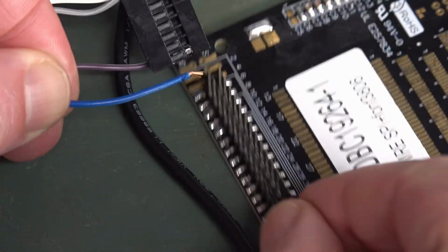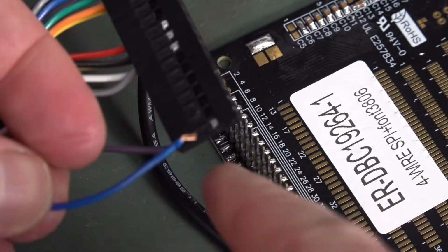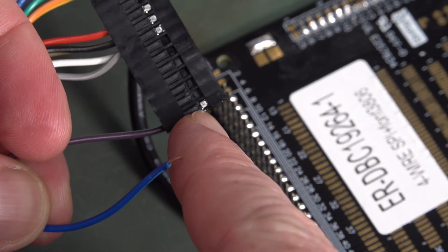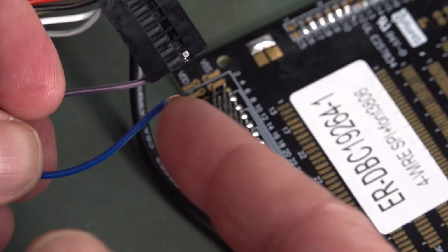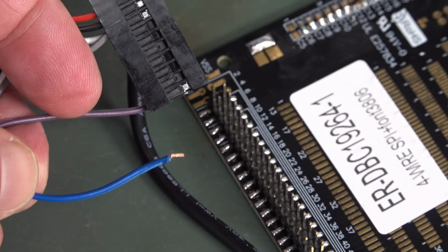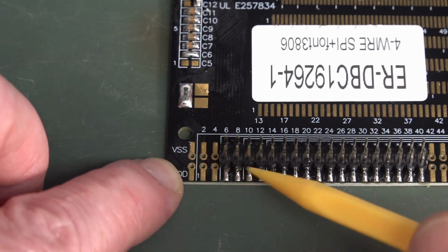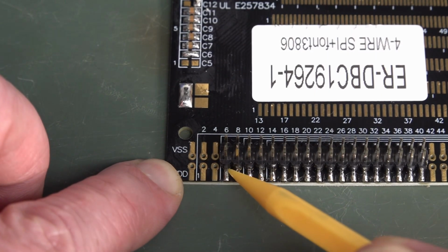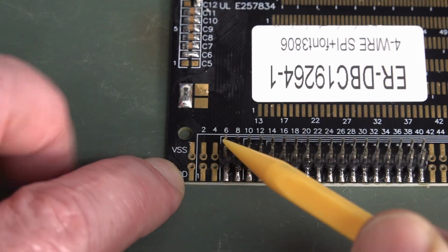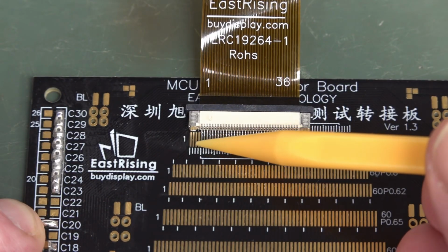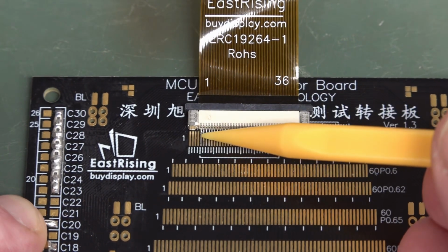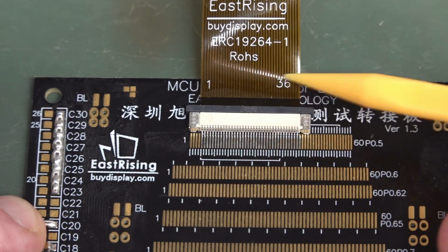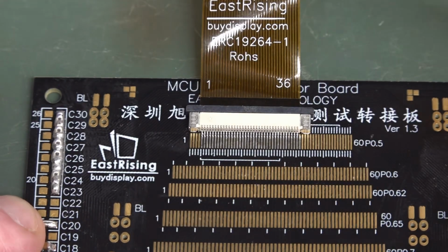And I thought I'd measure the battery current, but I've just come a gutser. I tried to pull the pin out here, which is the positive power pin, but the actual clip didn't come out and I pulled the wire out. Oops. One of the annoying things is that they've actually offset. They haven't put this right over to pin 1 over here. They've soldered it offset onto pin 5 and 6 over here, and they've done the same thing over to here, but so pin 5 becomes pin 1 here. So when looking at the data sheet, I've now got to add 5 onto it.